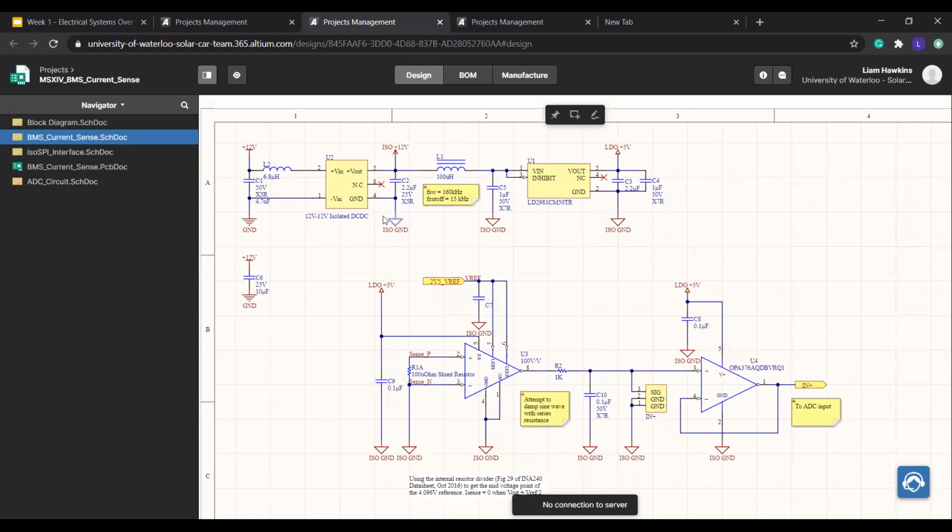Anyways, it will turn the output on and off very quickly to change the output voltage. And LDOs are basically just a resistor that will change its value to ensure that the output stays at 5 volts. So in this case, the excess power, so if you went from 12 volts to 5 volts, the excess power is dissipated as heat.